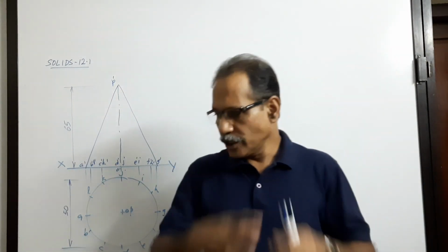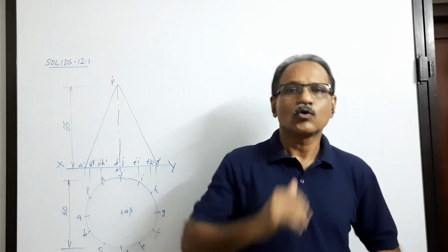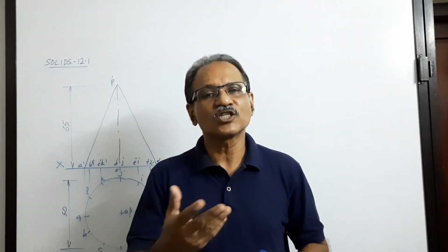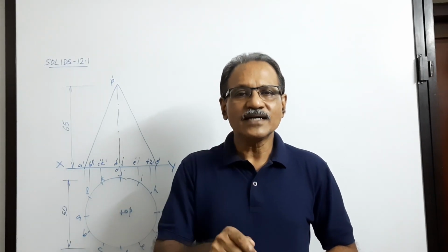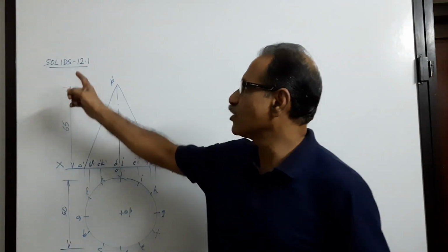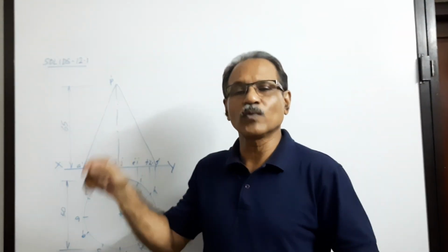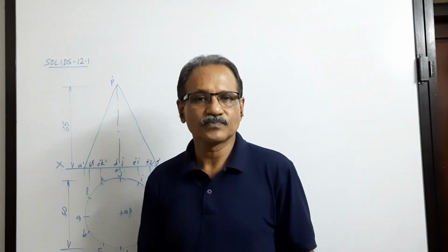Here we have a cone lying on one of its generators with the top view of the axis making 60 degrees to VP. We have done the same question by the redrawing method in video Solids-12. This is Solids-12.1, the same problem by the auxiliary projection method.